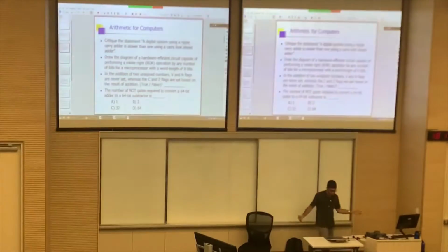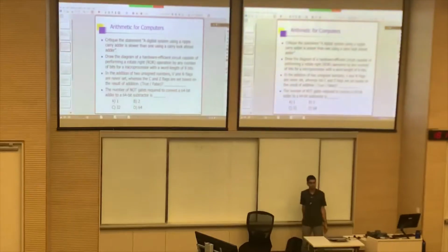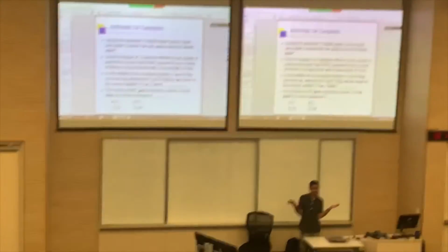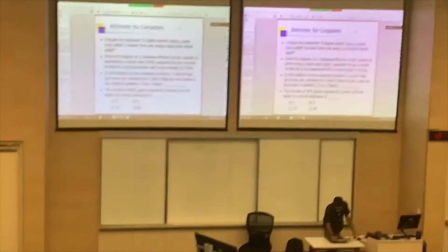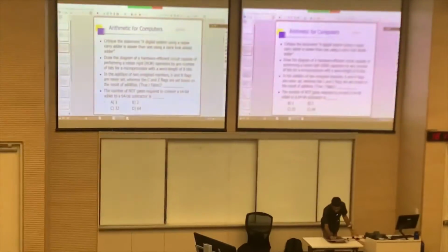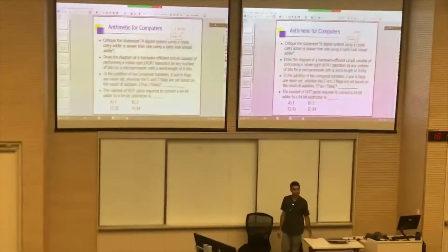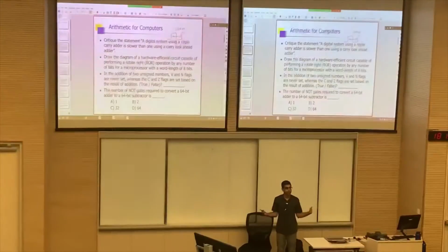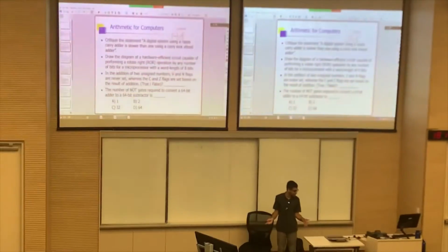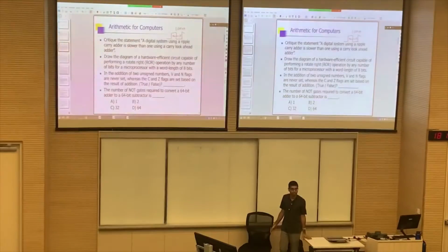Now let's say your timing is a bit more relaxed. You will have the ability to use a ripple carry adder in that scenario. Like for example, if your timing constraint is something like say 100 nanoseconds, so your clock period can be up to 100 nanoseconds, this doesn't sound like a stringent constraint. So it might very well be possible to use a ripple carry adder. So it depends on what your goal is. For a low performance circuit, you can afford to use a ripple carry adder, a low performance adder.